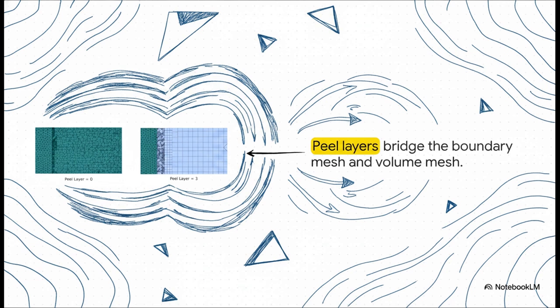By delaying separation and narrowing the wake, dimples drastically reduce this pressure imbalance. It drops the ball's total drag coefficient from about 0.5 all the way down to 0.2. That is a 60% reduction in drag. Add in the spin, which creates a side force known as the Magnus effect for extra lift, and that is exactly how a golf ball can fly so incredibly far.